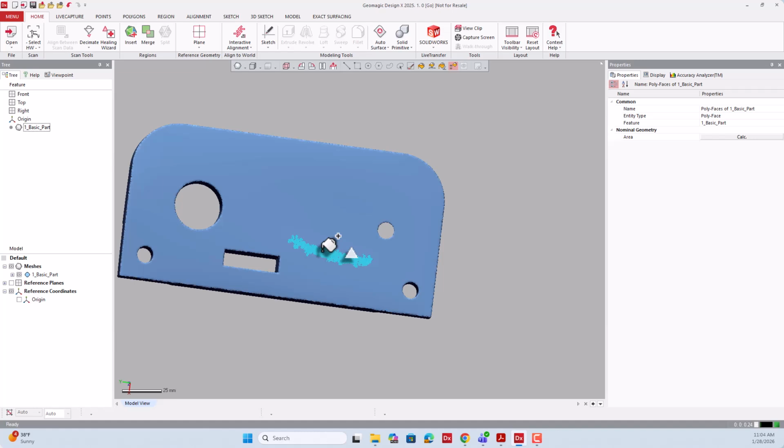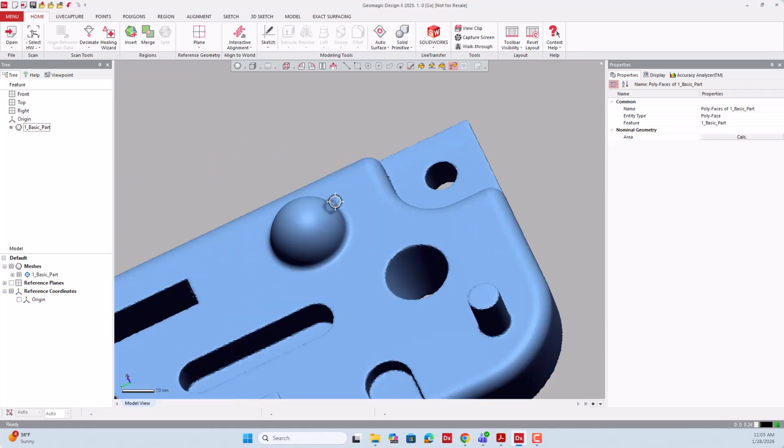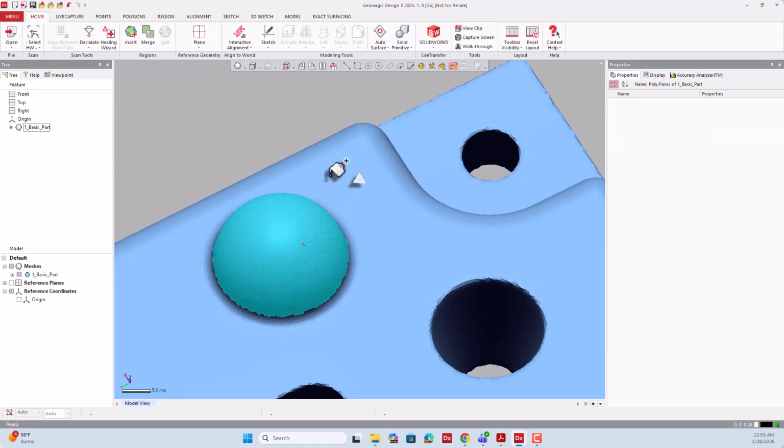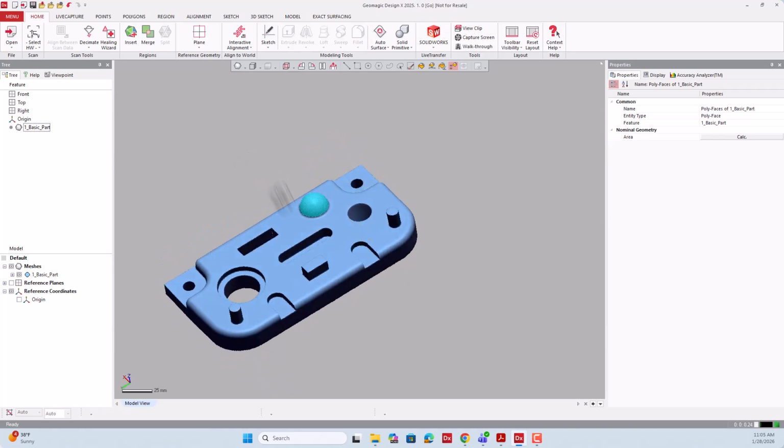Click, the selection is small. Now you have it on hold, and you're moving your mouse, and you're increasing the size of your selection. And you can apply this on any areas. So here you can come to this sphere. You can see that it has selected a good amount of points. I hold my mouse and I move it in one direction to expand my selection so that I cover all the faces on that particular sphere.